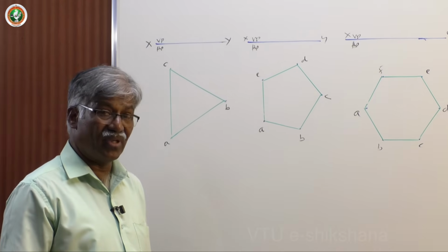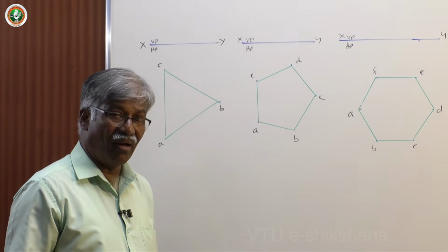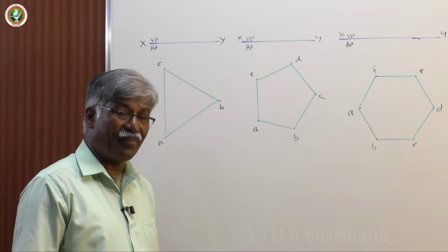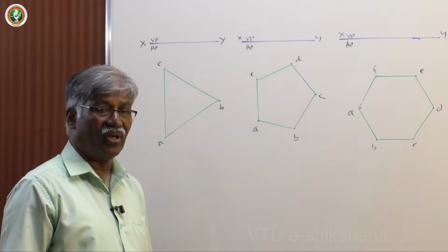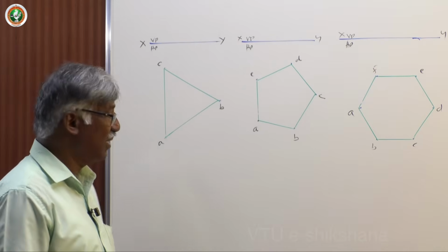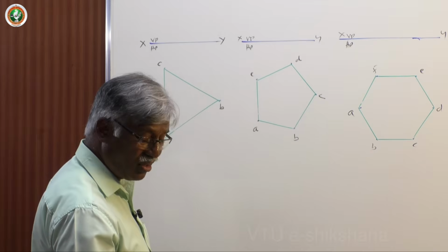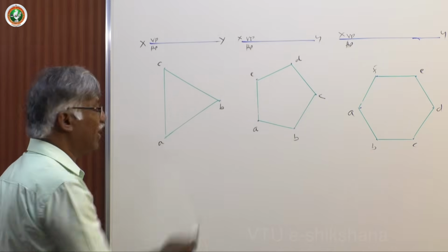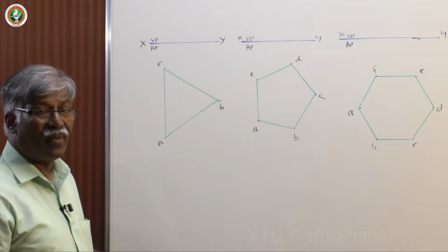Rectangle and square, if you keep in a particular position, all the edges are either perpendicular or parallel to VP, and naturally they are parallel to the ground. Definitely we can take all lines on 30-degree lines, but here just observe the lines are at different angles. Okay, so what we have to do is we have to go for the box method.